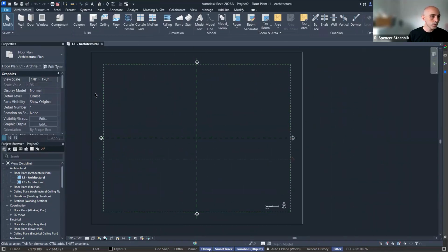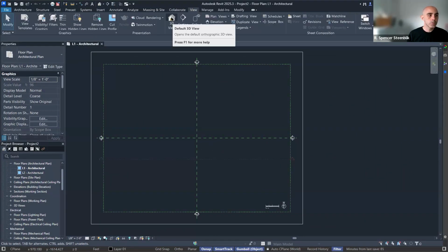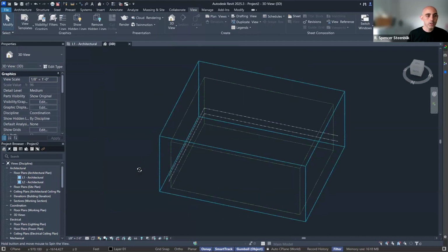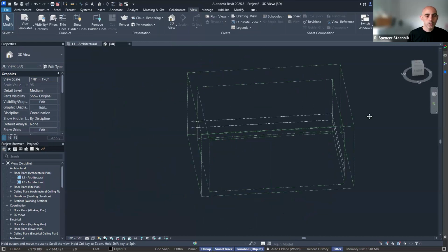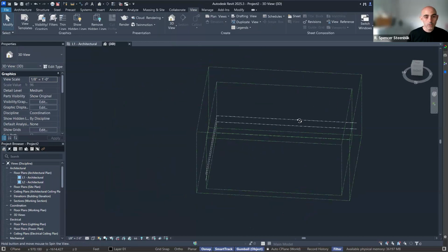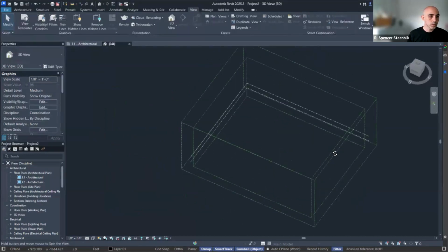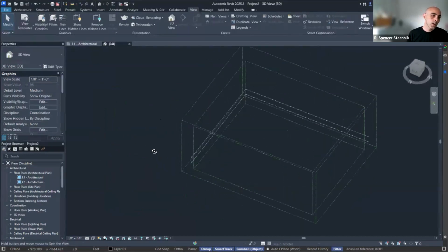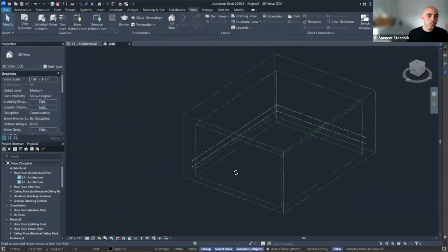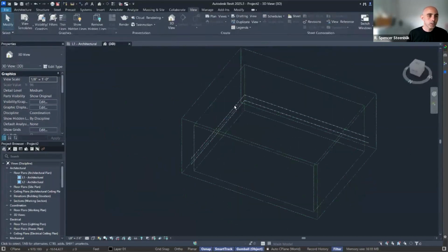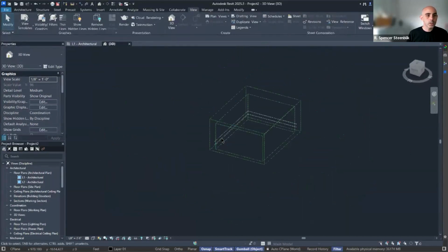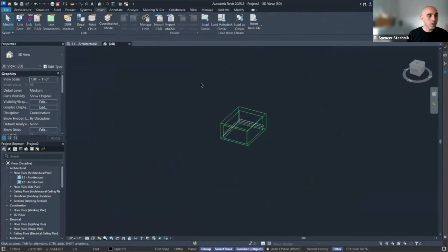And then when we're in the 3D view, if we go View, New 3D View, Default 3D View, we can make one. And you can use the shift and the middle mouse button to rotate around in that 3D space. And you'll do a fair amount of your work in a 3D view. Not all of it, but you'll do a fair amount in here. So we can start in this 3D view, and we can start by inserting, and it's pretty great because they natively support Rhino